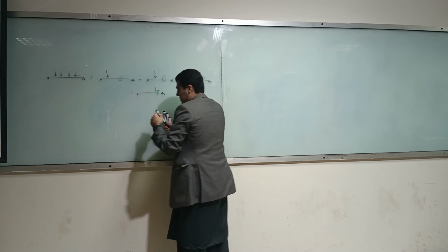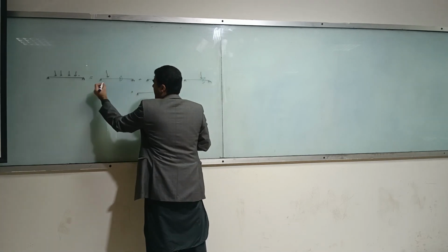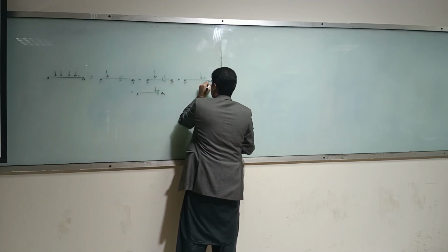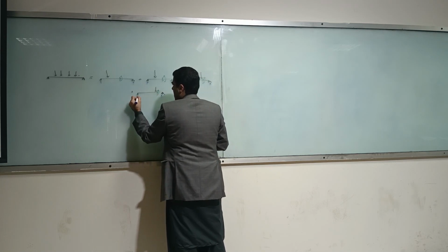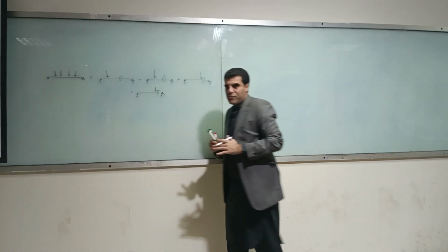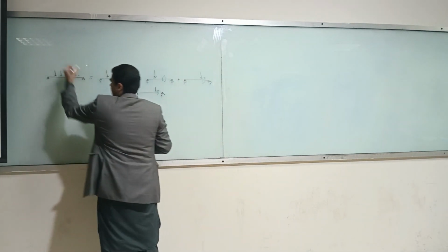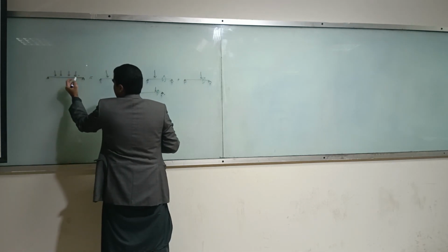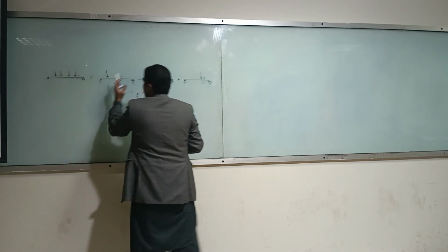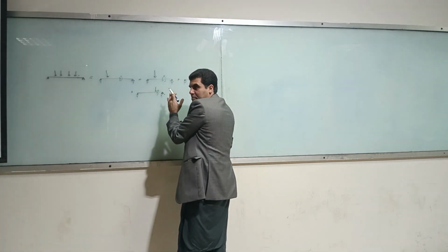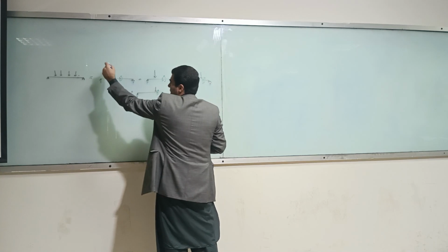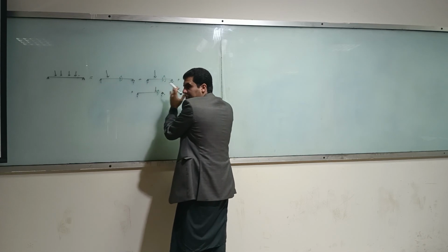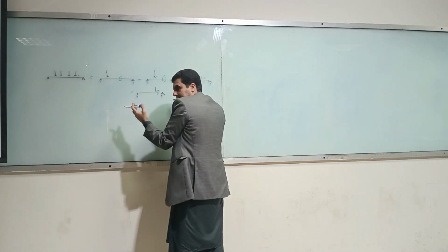Anything you are after, you can even have reactions. So a beam which is subjected to multiple loading can be divided into a series of beams or structures under independent loads, and then you algebraically sum up and find out that effect.